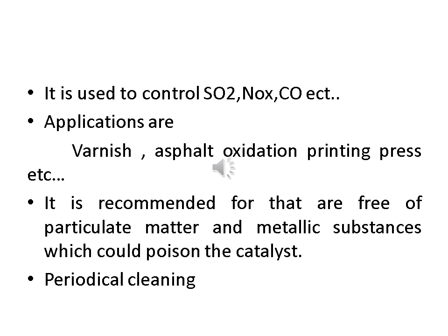Another one is the application. It is used to purify the emissions from industries like varnish, asphalt oxidation, printing press, etc. This type of combustion technique is recommended for gases that are free of particulate matter and certainly free of metallic substances, because those could poison the catalyst.